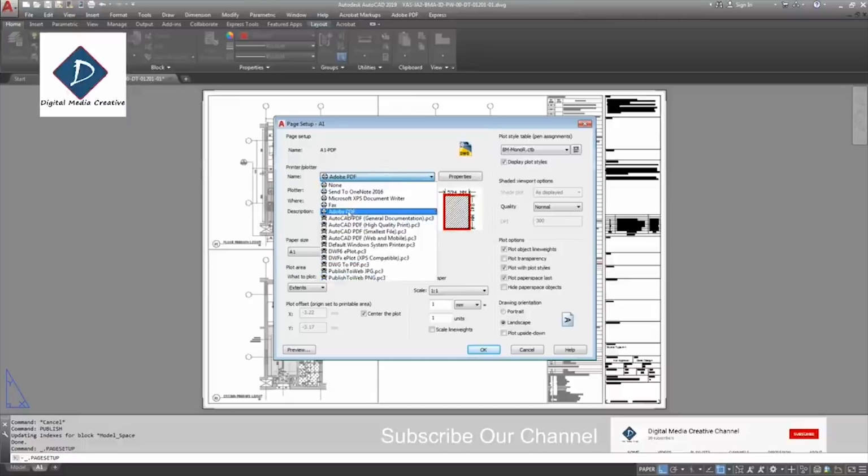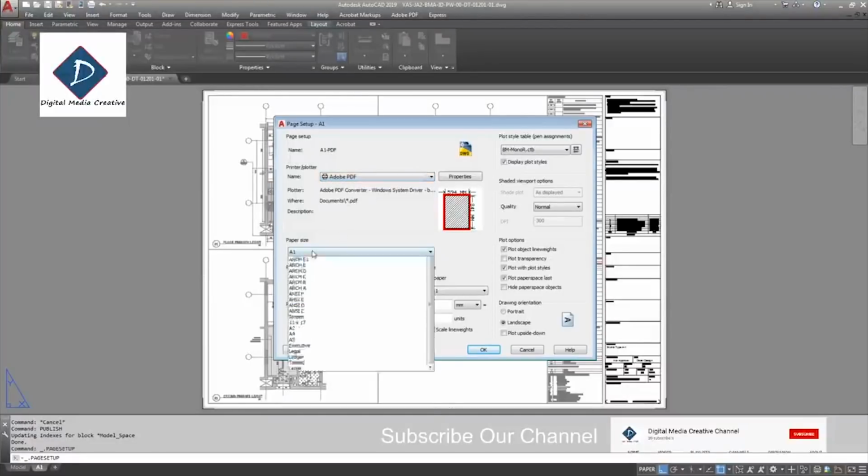Okay, so I'm just selecting the PDF for now, then I'm selecting the paper size, then I'm just selecting the extent. So select, make sure it's in center of report, also make sure it's in mm, and 1:1 scale should be. Don't make it fit to paper.